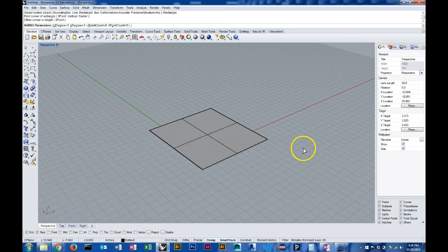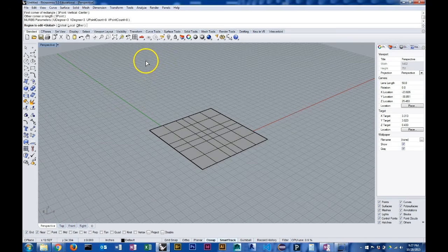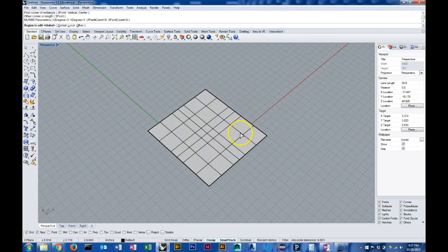Then it's going to ask me how many points in each direction I want to generate so that I can control the distortion. I set that to 8 here. It defaults to 4. The higher the number, the more points and the finer-grained the control you'll have, but it'll also be more difficult to get fluid distortions. But I will keep this option, and you'll see it's created some additional geometry here.